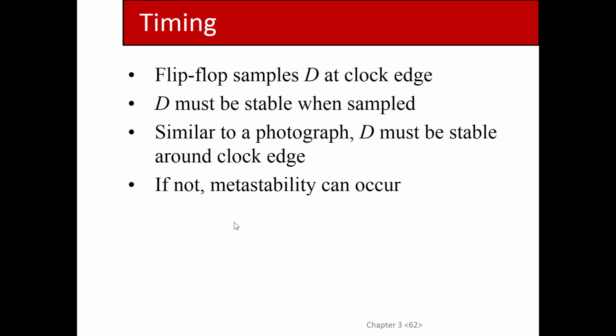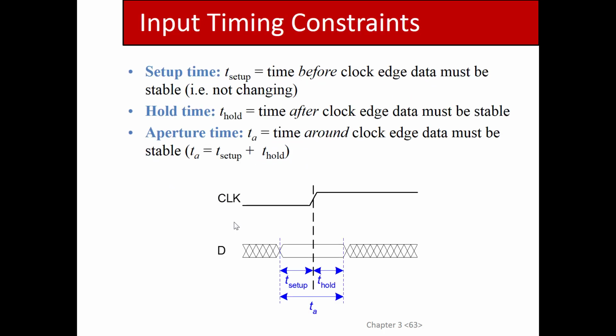So last time we also talked about timing a little bit. So registers and flip-flops have these timing constraints called setup and hold time, meaning that you have to ensure, when I say you, I mean usually what I'm talking about is the tools that generate the hardware.